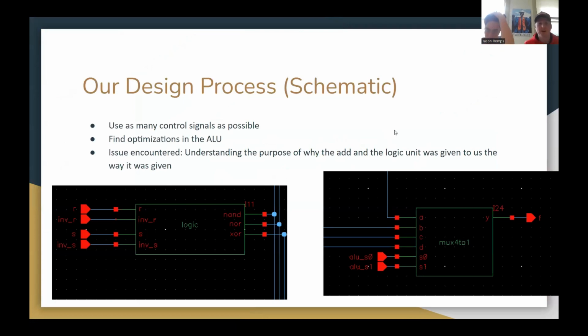In terms of the design process, we had many optimization steps, going with the most obvious, simple to implement design initially, and then optimizing to get our size down throughout the MP. A big area of optimization was the ALU, where we had initially implemented all 8 functions of the ALU independently, and then put them through an 8-to-1 mux at the end. We realized that the operations could be classified into 4 classes and then decided upon based off select signals, rather than just deciding upon based off the opcode, the section of the opcode that decides the ALU operation. This allowed us to go from a massive 8-to-1 mux down to a 4-to-1 mux, which saved us a lot of space in the overall design.